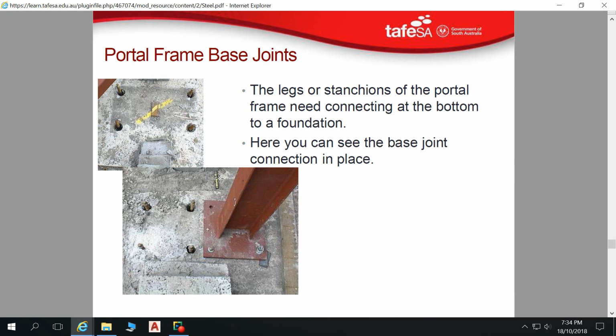That Dynabolt, in best case scenario, its strength will be taking out a cone-shaped chunk of concrete with it that's around, sort of that 30, 40 millimeters in diameter and 50 millimeters deep. That's not very strong. And that's best case scenario. So those Dynabolts, yes, they might take a cone of concrete out with them in best case scenario. Worst case scenario is they just pull out.